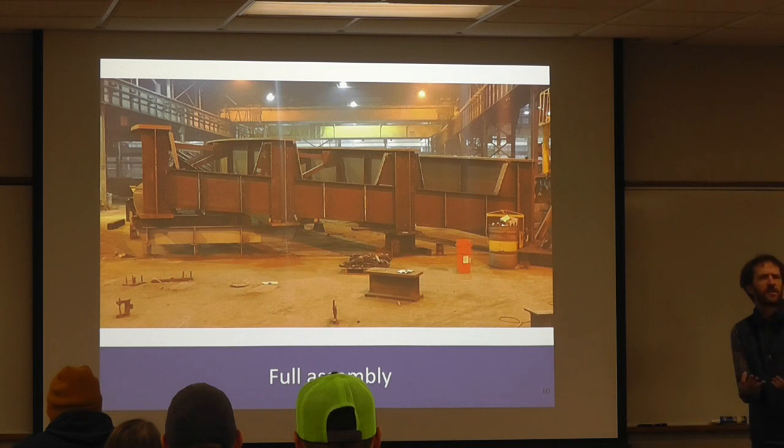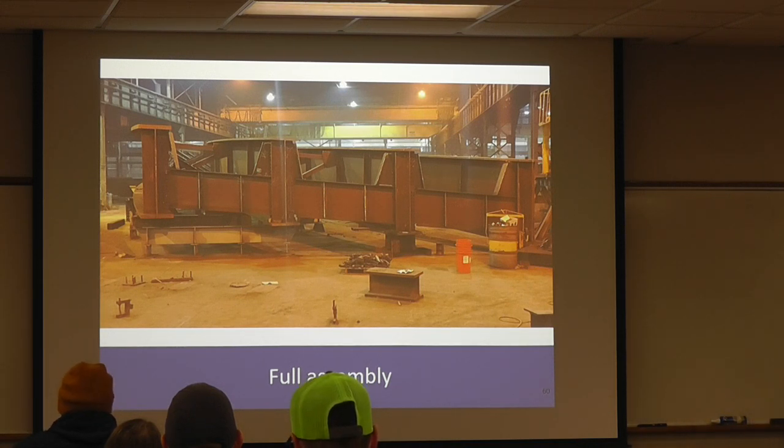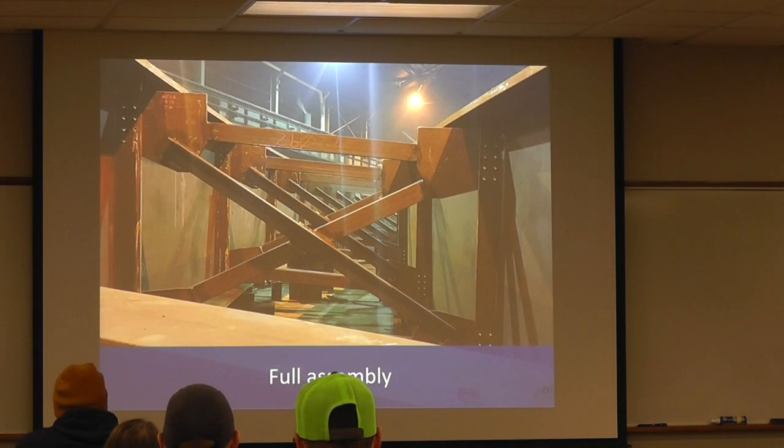They have to manipulate that in the air. So you can see where we start to have fit-up problems, or have the potential to have fit-up problems. That's why it's important for you folks to know, was this fabricated as a line or an assembly? Right? Line assemblies generally come together pretty easily with not a lot of effort. Here's just another photo, that whole forming operation, getting those diaphragms installed.